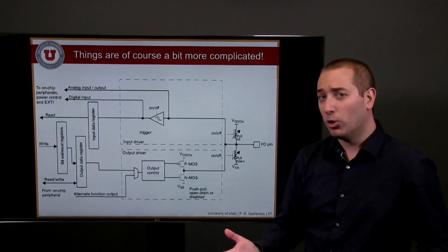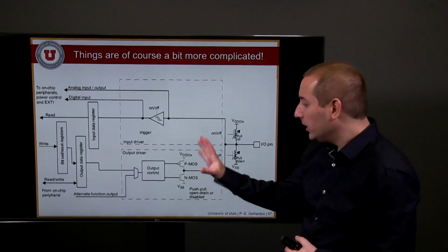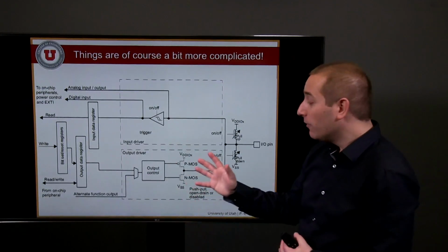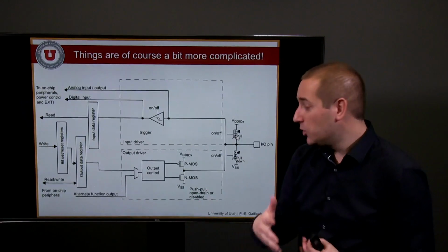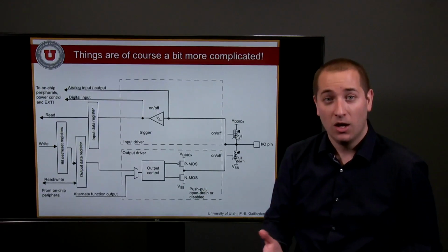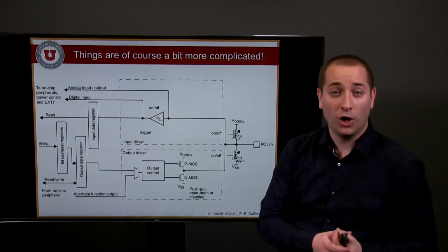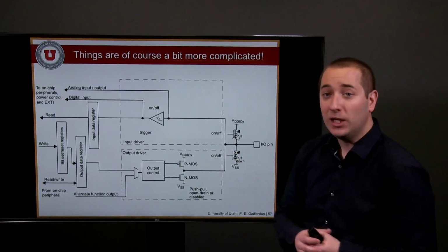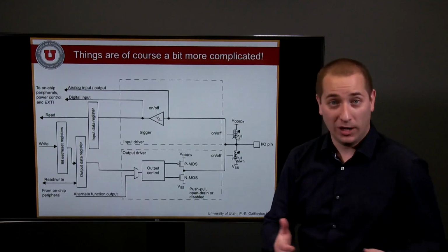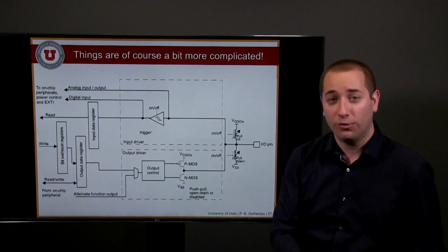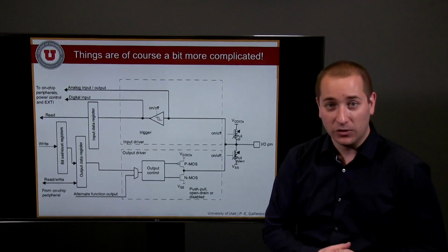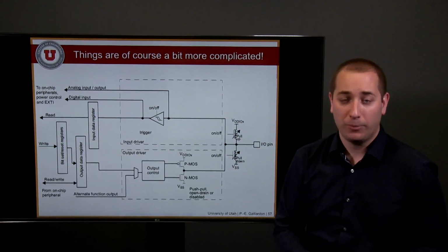While things do look a little bit more complicated, controlling those different functions will be done very simply by writing some control codes into specific memory locations. These memory locations are called control registers, and they will be most of the focus of our labs this semester, in order to understand how to control various peripherals using these techniques of memory mapped control registers.